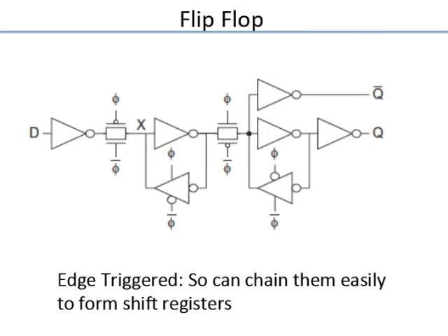The thing with the flip-flop is that you can easily chain them, though you have to pay a little bit of attention, and I'll come to that, to something called hold time. But you can chain them and then things will work properly. With a latch, you have to be very careful when you chain the latches, because a latch is transparent for a duration, maybe half the clock cycle. When you chain them, you have to ensure that the two latches next to each other, like latch 1 feeds latch 2, don't become transparent at the same time.